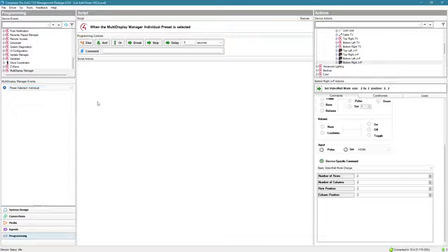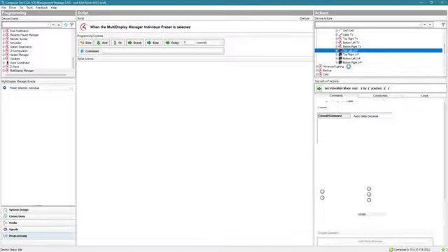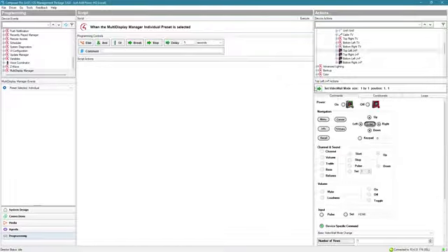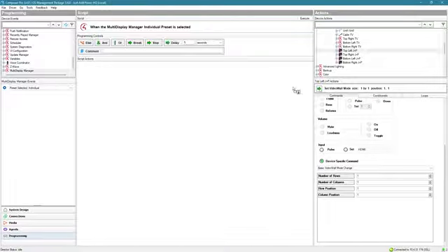but it's kind of stuck in wall mode. If I hit individuals, nothing happens. Even if it switches to different sources, I've got the corner of 4 different sources. So when we do an individual mode, we have to tell the Just Add Power receivers to be a single television. So again, we go down to basic video wall mode change, but this time we leave all the numbers at 1. Rows, columns, row position, column position, all at 1, because they are just all by their lonesomes.